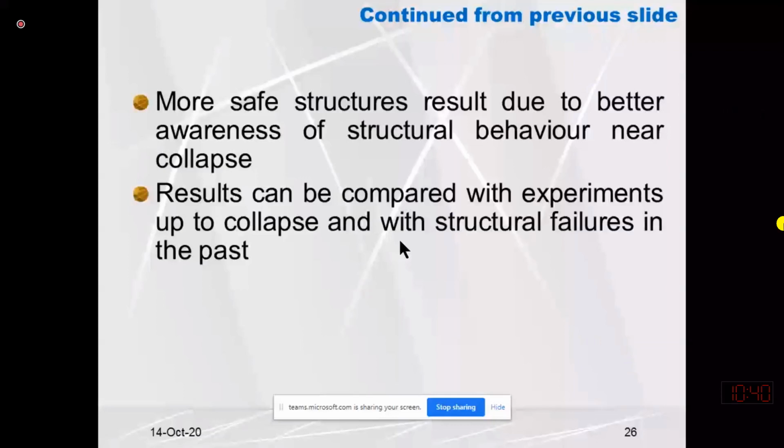And also, if you are overloading it, you can observe whether the failure is a shear failure or a lateral failure. So if in the field we have seen some failed structure, we can investigate or evaluate the reason why this failure occurred. Was this failure due to the maximum shear stresses or bending stresses?